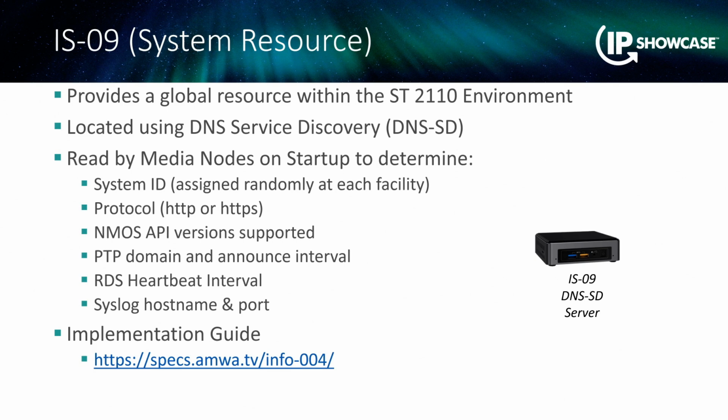It's this thing called system resource, which is just a little program that's running on a little PC. It could be a little NUC server. It could be something built into your control system. And it's advertised constantly. It's saying, here I am, I'm your DNS-SD server. Come talk to me if you're a new 2110 device, and I'll tell you everything you need to know. So you power up, you get all that info, and it can be set automatically. So some human doesn't have to run around 1,000 pieces of equipment and type in all these different pieces of information. It can go extract it automatically. Big time saver.